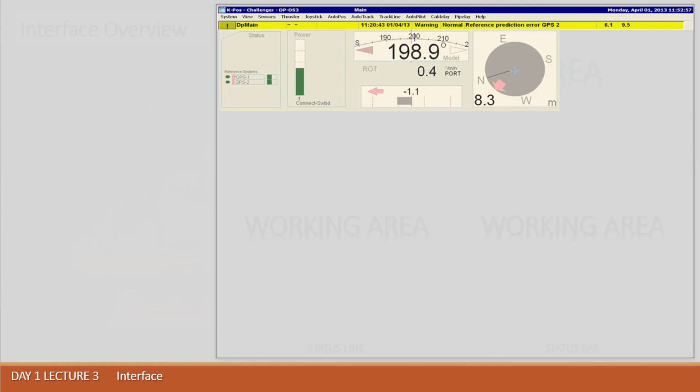In auto position mode, here is shown the deviation alarm presetup. The same story in solid or dashed lines. In solid lines, the presetup for position deviation is shown when the setup is done. This area is click sensitive. When you click here with the pointing hand with the left click of your trackball, you will receive immediate access to the alarm setup zone. In my case, 8.3 is a deviation from desired position.